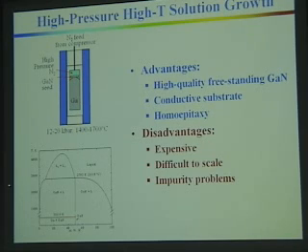Here's a phase diagram that we calculated for gallium nitride. You can see it melts at about 2,500 degrees C, making bulk crystal growth very difficult. There is also a liquid-liquid miscibility gap that exists here, and so if you're not right on solution, or your nitrogen leaves from the vapor pressure, you can see you can very easily pull over to there or get off stoichiometry.